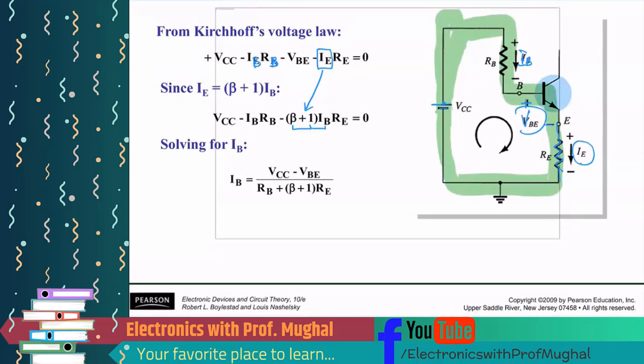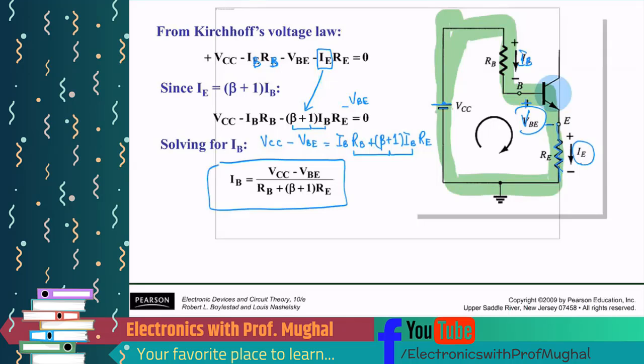If I rearrange this equation, it will be VCC, and this is minus VBE here also. VCC minus VBE equals IB RB plus beta plus 1 times IB RE. In these two terms, if I take IB common and find IB, I get this equation right here. Everything that comes out common goes to the denominator: RB plus beta plus 1 RE.